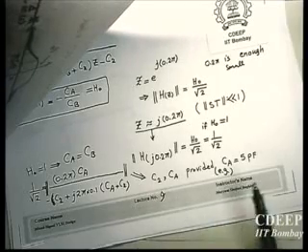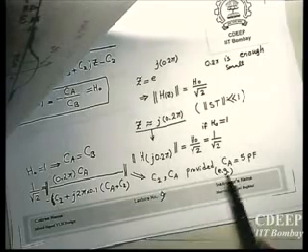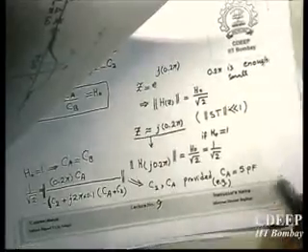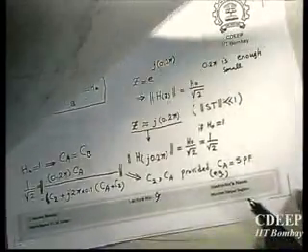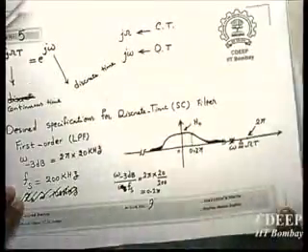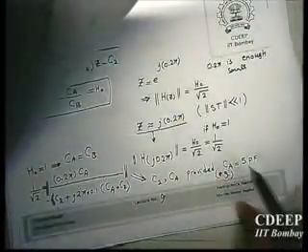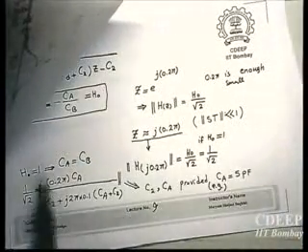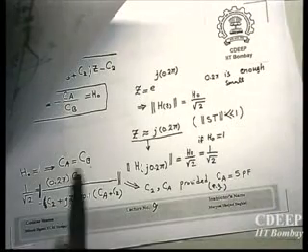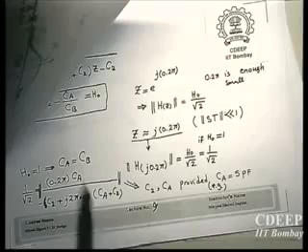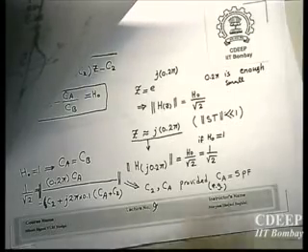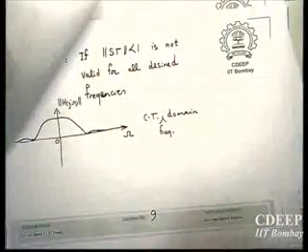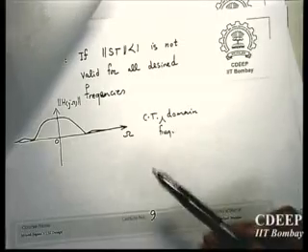Anyway, in Z domain, just by knowing these characteristics, you can get the values of the capacitors. You have 3 capacitors and 2 conditions, so you assume some value for one of them and then you get the other 2. In fact, from the gain condition we have these 2 equal, so the number of variables is reduced to 2. So this was yesterday's example.